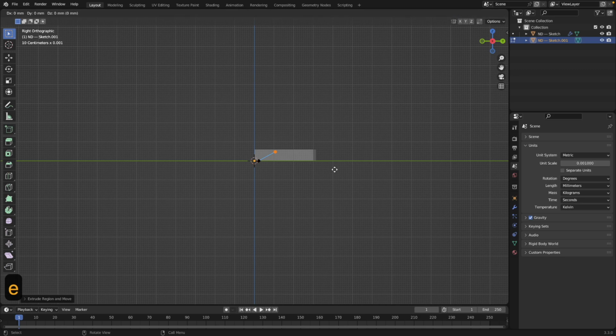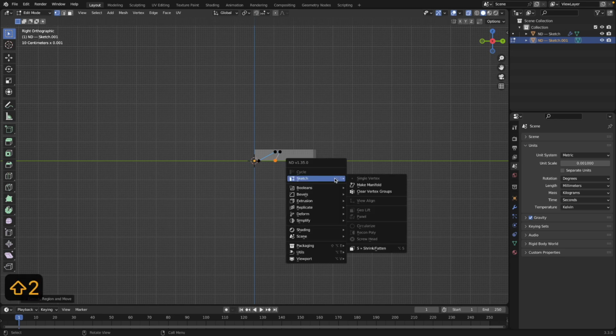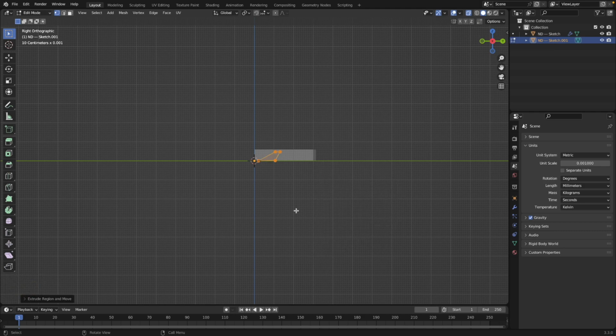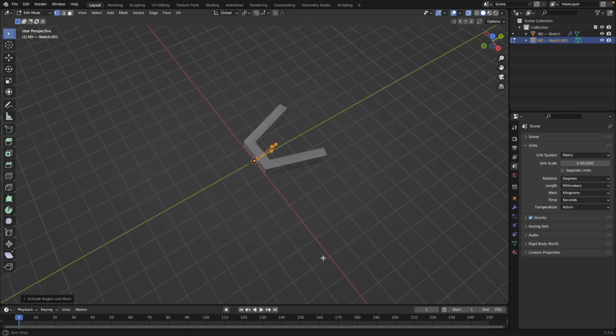We're gonna extrude it in the Y direction this way, just to give it that little flat top. And then this time, instead of extruding it straight down, I'm gonna extrude it kind of back this way so that we have a little bit of overhang from our ends. That's a little extra thing that we didn't do last time. And then with that, we will make Manifold to solidify, or to fill it in at least.